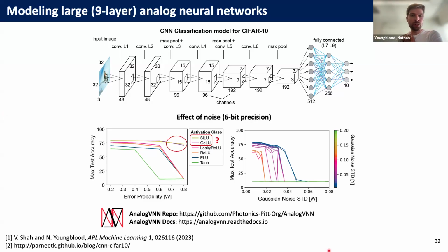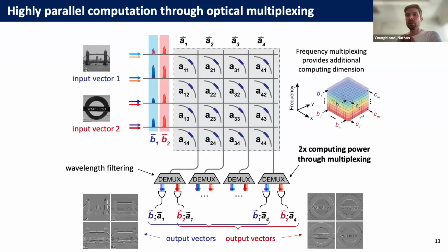Yeah, that's a good question. So for example, here, right? You have to have different wavelengths so that you don't get interference and beating and stuff like that as you send light through these waveguides. The main limitation is these directional couplers. So first of all, the directional couplers need to be relatively broadband, and that gets worse the closer to 50% coupling you get, right? Just from the, it's proportional to the sine or cosine coupling equation. So that's one issue. There's work to make that broadband.